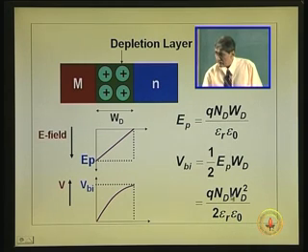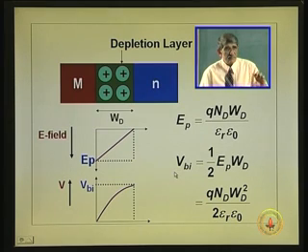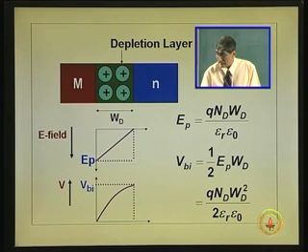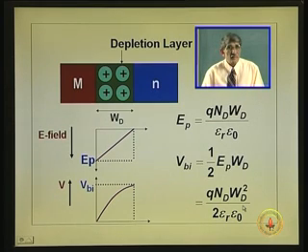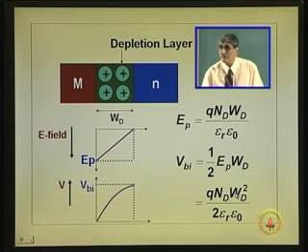Now, that means once you know VBI, that is why we evoked that. We said phi Bn equal to VBI almost. So, that is 0.953 for gallium arsenide. Now, what we want to see is, that VBI is fixed, because once phi Bn is fixed by Eg minus phi naught, that is fixed, and once that is fixed, I can control the width of the depletion layer by changing the doping. Now, if I increase the doping, WD will fall.